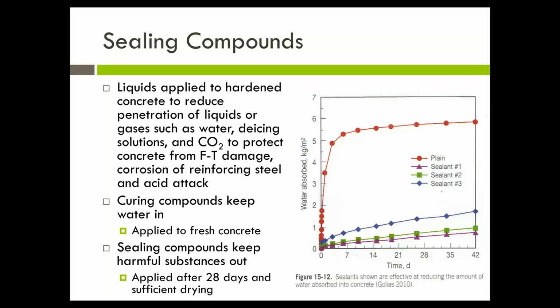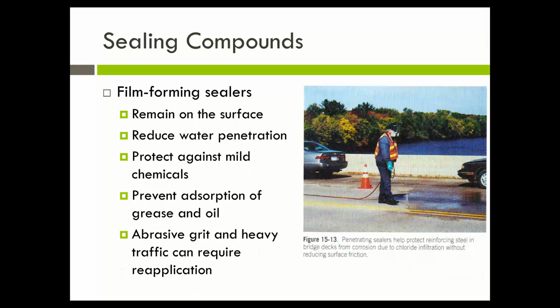And so you see these materials that are sold as cure and seals. And of course they will cure or seal, but they can't do both, because if you put them on early on, then they're only good for curing, because hopefully you won't get any penetration into the pores because the pores are full of water. And then later you can use them as a sealer, because then they'll penetrate into the pores. But since you would require the pores to be both full of water and empty of water in order to be a cure and seal, no such thing exists.